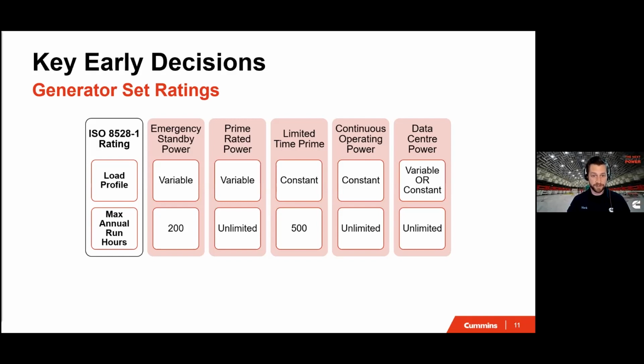So not every region of the world has as reliable utility power as we are used to in the United States and North America. And so this good faith estimate is intended to separate out standby gensets for otherwise reliable utilities from gensets that should likely go to prime, honestly, with utilities that comparatively have more downtime. So to keep things simple, if you're a standby application in the United States, you're most likely going to be asking for a standby generator set.